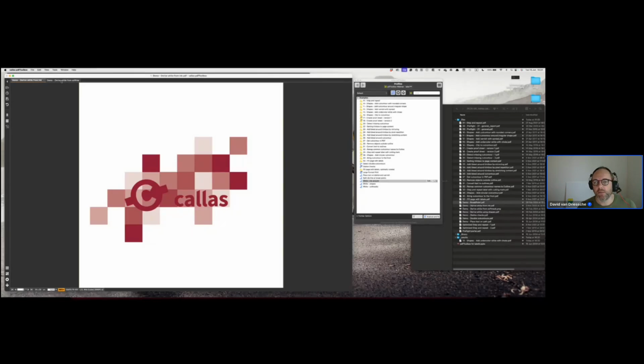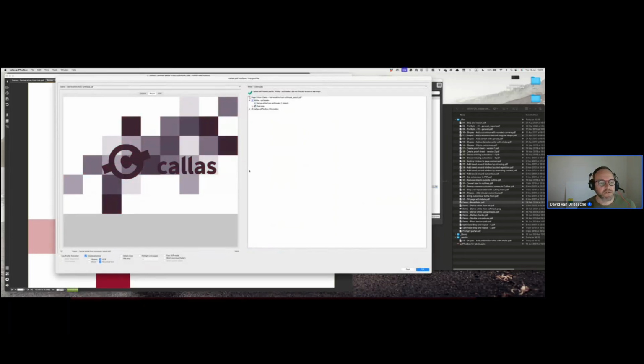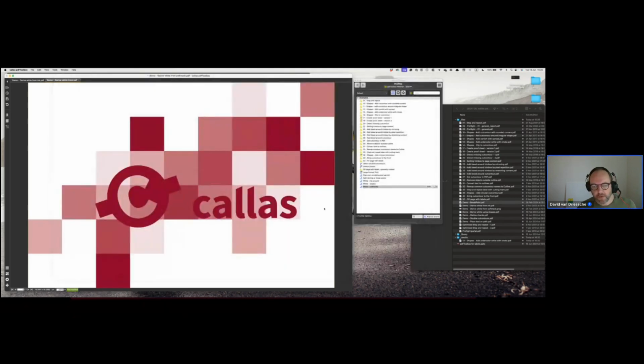In the shape technique, you can only look at the actual shape of the objects on the document, but the white is always 100%. Here I can look at the amount of ink and then adjust the white that is generated. And the same thing for files that have soft masks, like the one that I have here, where I have a fix-up that specifically adds white according to the soft mask information that is in the document. Yeah. It's a very good example of what you typically see in PDF Toolbox.